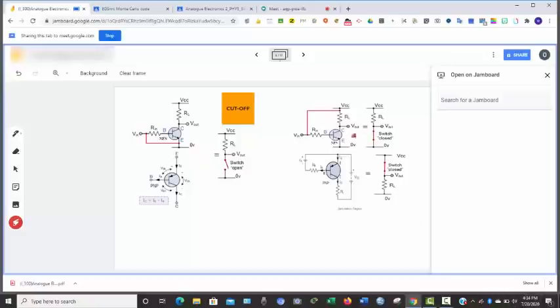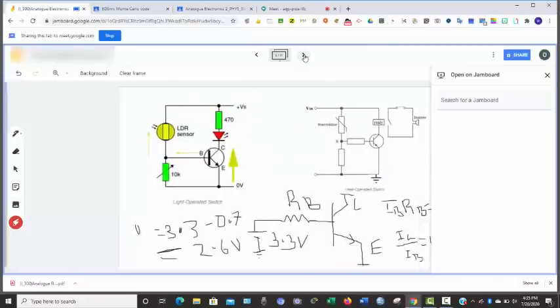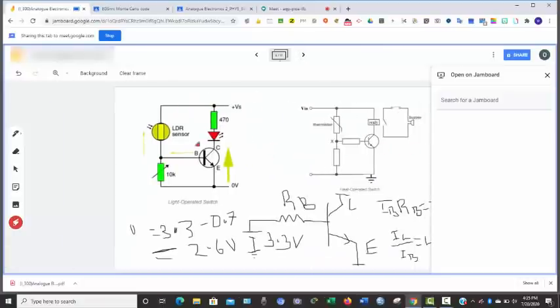But when we supply some voltage to the base, there will be flow of current, and if it is more than the VBE, then we'll be able to have VCE or V out, and then we'll be able to have IC. And with that, if I want to do anything in this neighborhood, I can plug something to this place and I can have voltage. And if I remove the voltage at this place, the voltage at this place too will not be there. And I can easily make an arrangement with this one. Either I put a thermistor or I put an LDR in that region, for example, like what we have in this case now.